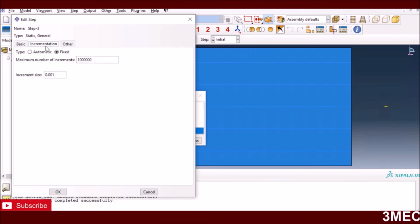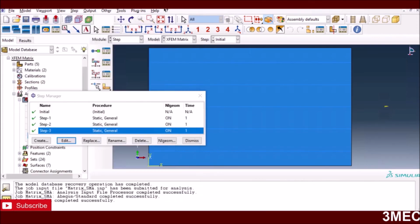Again, I'm using stabilization, and in this case I have given a fixed time increment because it may take a long time because of the cracks and surface interactions. So I'm using a large number of increments, and I say to use an increment size of 0.001 because there is not much of the loading or unloading, it's only unloading in this case. So I have assumed this value, which is more reasonable, but again you have to play around with this number to come up with a more accurate prediction. Or again you can go with automatic as well if you want to. I just wanted to reduce my time for simulation.